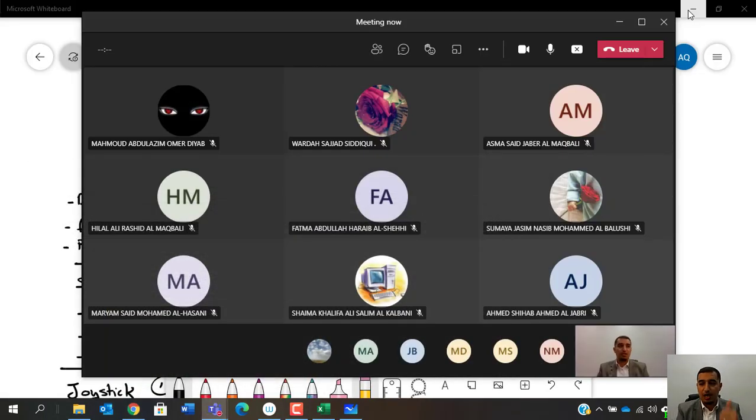So in that project you have a joystick, which is analog to digital converter. You have the DC motors, which you need to control the direction using the normal ports, and the speed you have to control using the timers and counters, like we did in class. So as the joystick moves, as the resistance changes, then you will have to control the speed using the timers, counters. Remember, the joystick will change the direction up and down, so you need to change the direction of the motor in the same way.